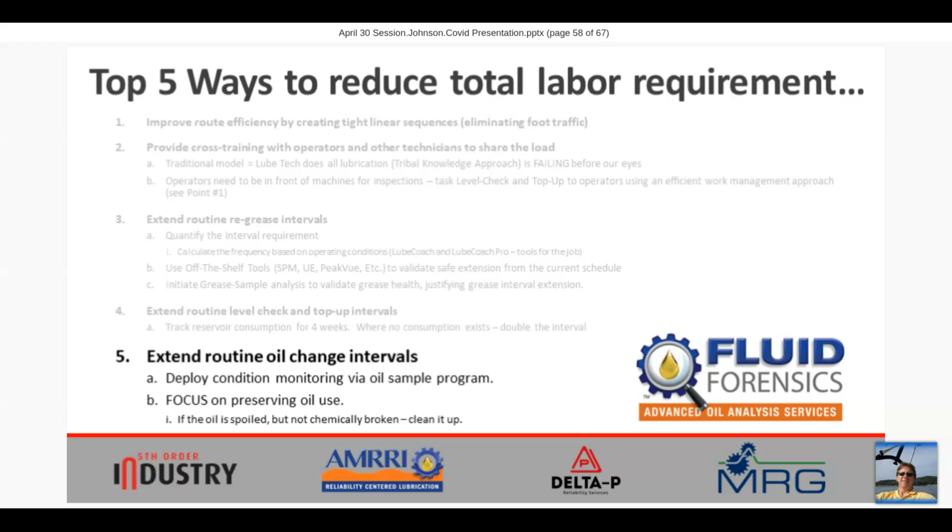In my ongoing oil analysis surveillance for several plant sites, rarely do I see a bona fide need to change oil. And those instances will only occur when there's substantial chemical contamination, cross-contamination between process contaminants in the oil or different lubricants than the one that should be in place.